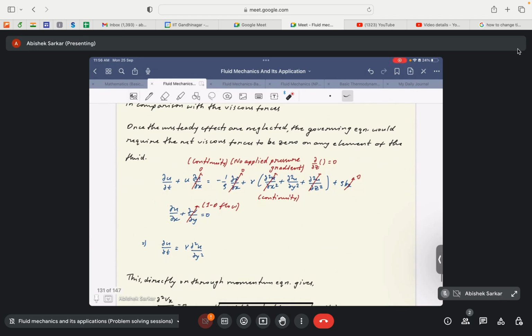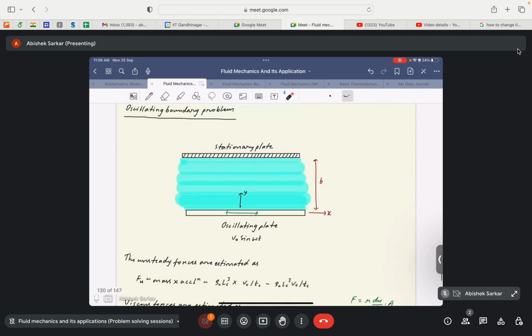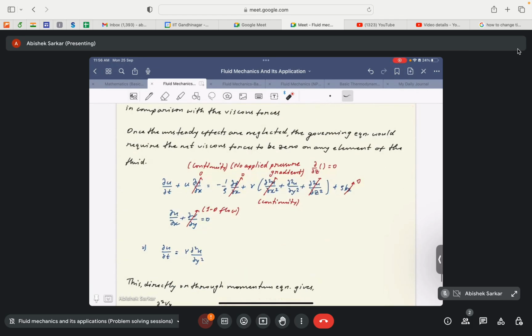Okay. So, one more important assumption that we take before solving this problem is that rho is constant. The density remains constant. The flow is incompressible in this case. But that ideally should come to the mind of the researcher who takes the problem: if we take the fluid to be water, then the water itself is highly incompressible in most scenarios, and the flow velocity itself is very small or within the subsonic range. So the compressible nature of the fluid goes out of the context immediately. But then also, we need to check again and again.